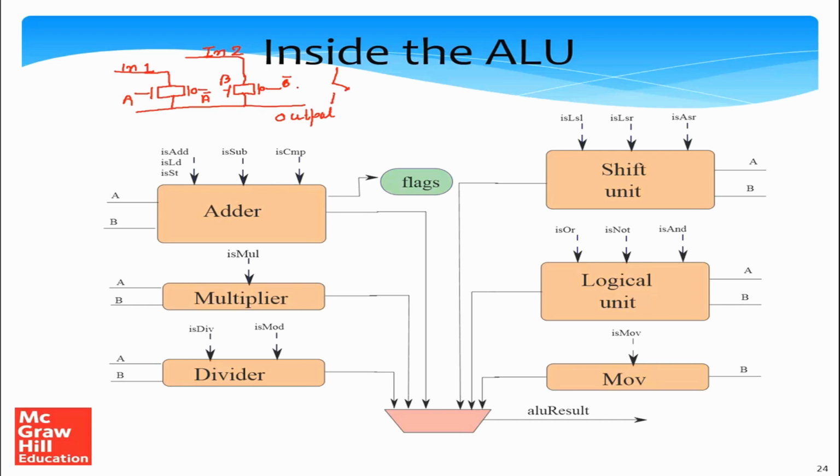You can think of it that if this is a switch, the switch is absolutely not connected. And similarly, we can connect 10 other inputs to the output wire, and as long as we ensure that one of the transmission gates, which is essentially just a single pair of NMOS and PMOS transistors, is enabled, meaning transmitting current, conducting, then the output will be equal to that input, and the rest of the inputs will be floating.